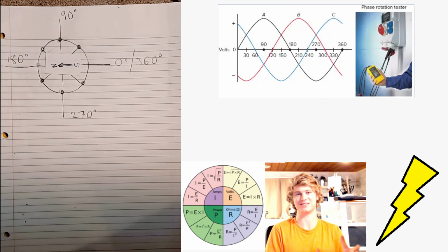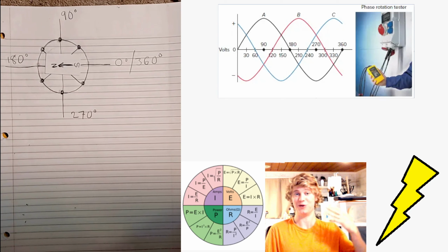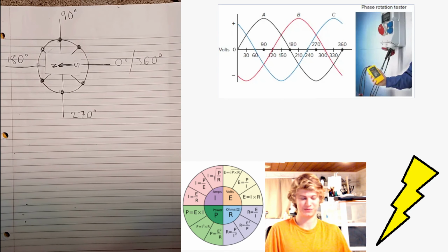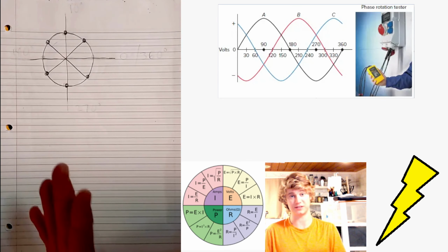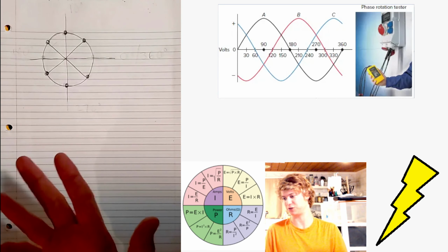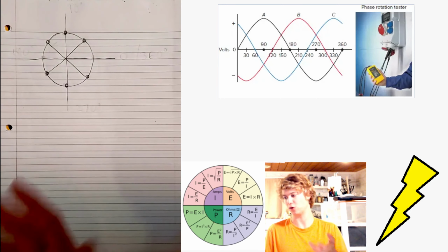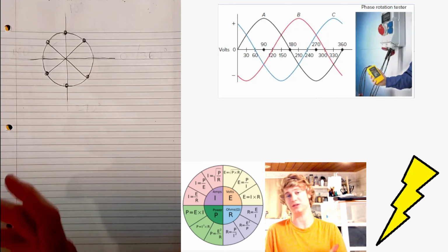Okay, so that's why a 3-phase system is superior when you have larger loads. For residential and homes, it's practical to just use single phase. You don't need 3-phase. You only actually need one of the phases of a 3-phase system, which is what we have. Okay, so this phase sequence that we see here, where we have A, B, and C following at 120 electrical degrees apart, is not only a 3-phase system, but the phase sequence for this system would be A, B, C. The phase sequence may be reversed by either reversing the direction or rotation of the alternator or interchanging the connection of any two of the three wires used for the transmission of the three-phase voltage.